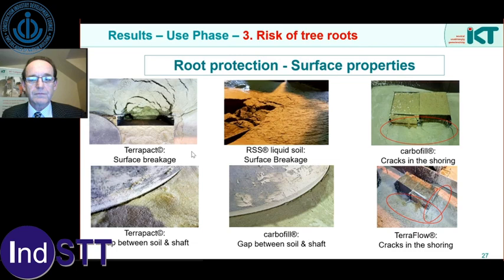Looking at the tree roots, when you have tree roots growing in or near a pipe, it's usually because it is following the path of least resistance. So a series of cracks on the surface here would allow tree roots into this structure, but as we discovered, it didn't go all the way through to the bottom. Also here around a couple of sides of the manholes, we're seeing a bit of shrinkage. And we also got odd little bits of shrinkage or cracks around the edge of shoring, which would be routes for roots to get through.